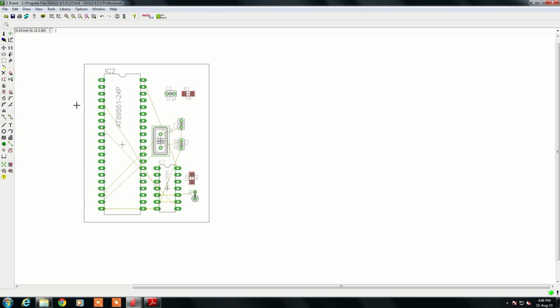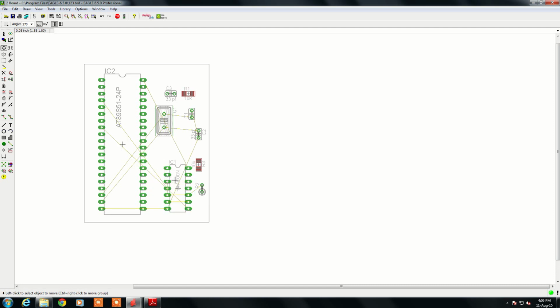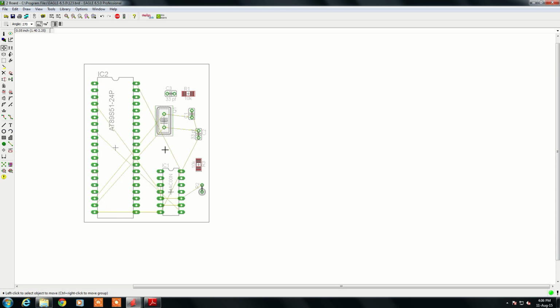Since there is a possibility of some percentage of not routing, you can replace the components, maybe slightly better organized, so that next time it will be able to join all the lines. So you need to simplify the path so that it will find some space to join the tracks. While designing, always have some manual routing for special signals like VCC, ground, or some clock signals, and use the auto routing facility to join the tracks